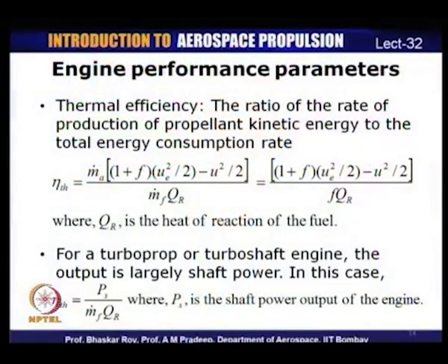Thermal efficiency is defined as the ratio of the rate of production of propellant kinetic energy to the total energy consumption rate, which is the numerator we have already discussed divided by the energy consumption rate, the mass flow rate of fuel multiplied by Q R, the heat of reaction of the fuel. This can again be simplified as (1 plus f) into u e square by 2 minus u square by 2, divided by f into Q R, where Q R is a property of the fuel.